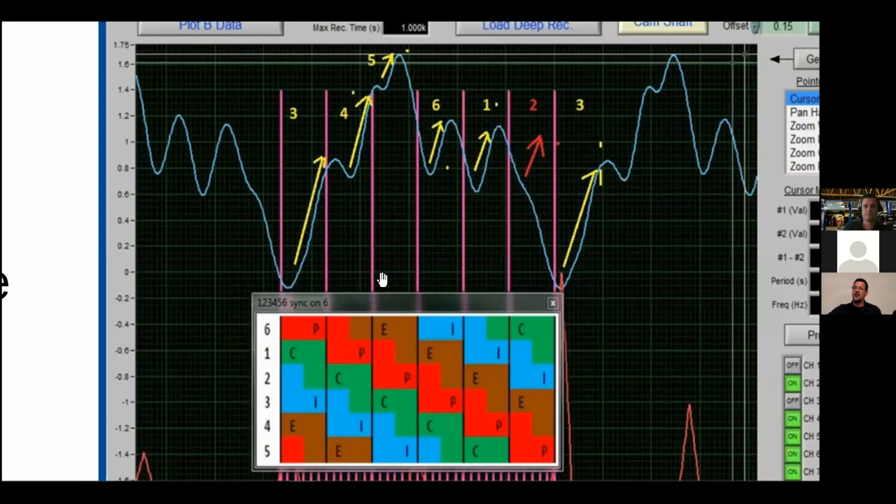Excellent. Now, again, vacuum goes up when a piston contributes. So we've got a contribution, a contribution, a contribution. And although overall manifold vacuum dropped for a moment because the engine slowed down, number 6 is still contributing, and so is number 1. And so is number 3, but number 2 is not. So I hope that makes sense.